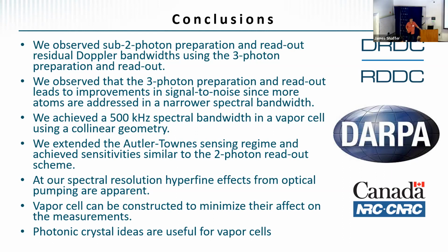So what we really cared about was to try to get a uniform field inside first, and then that was varying the whole parameters and looking at that with electromagnetic simulators like LEAP and HFSS, and then secondarily to then choose the hole, I guess the filling ratio or something, to try to match the dielectric constant.